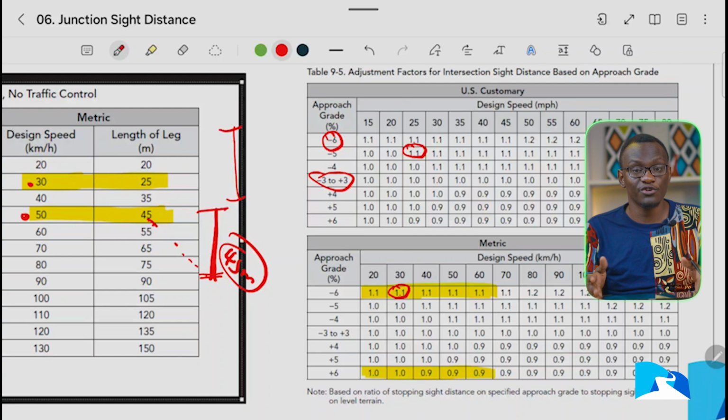It was very important for you to understand, one, the side distance needed on the minor road to see the car on the major road, and also the departure into that. So that's case A. There's no intersection control. What distance are you going to look at? So we have a second case where we have a stop. Someone is always told stop, whether this or that. And then what do we consider in this case?